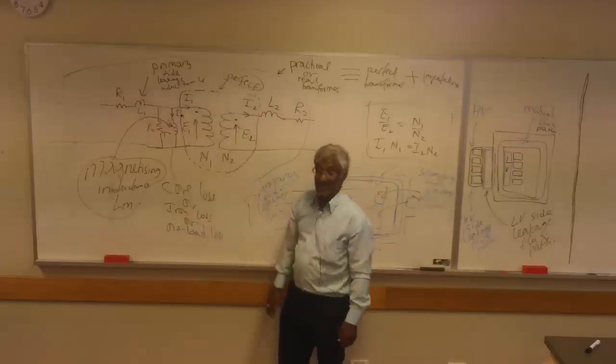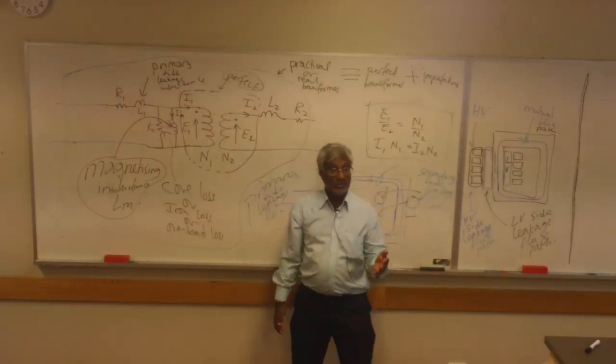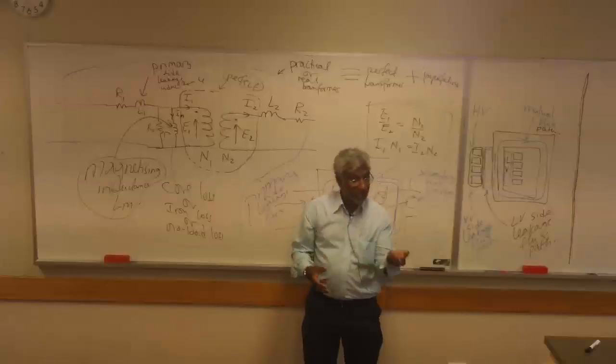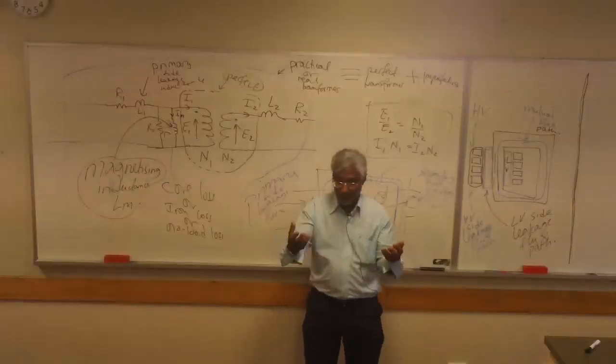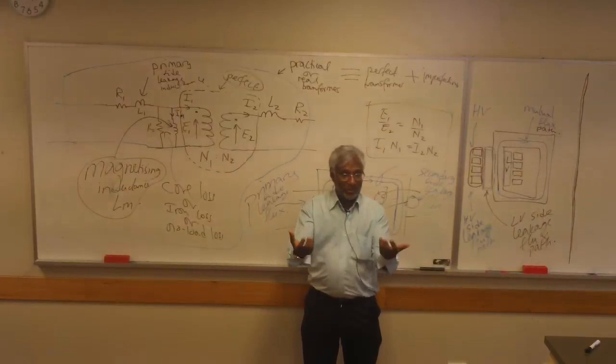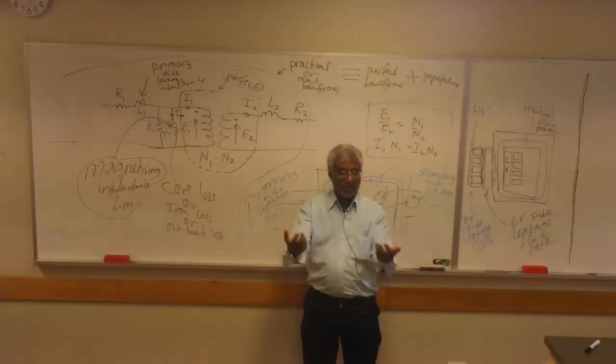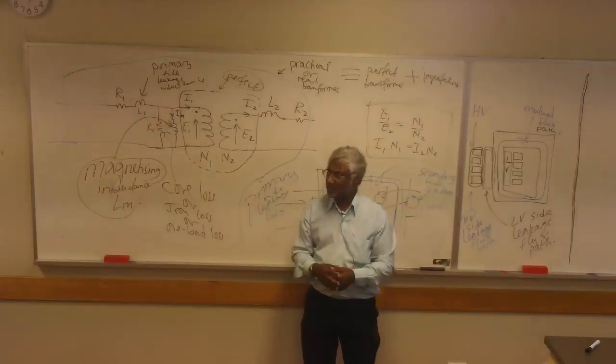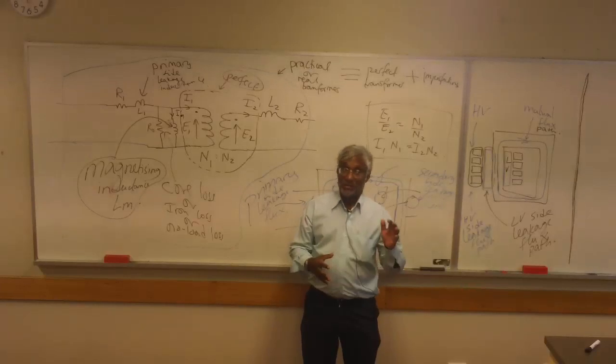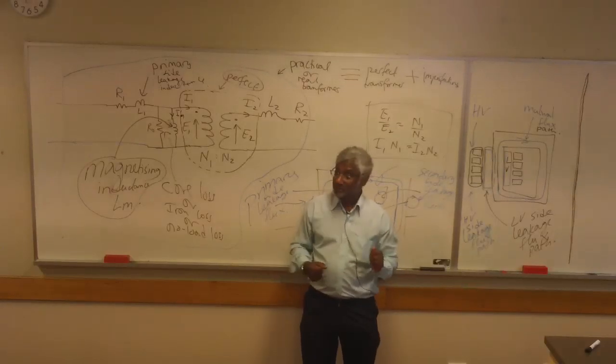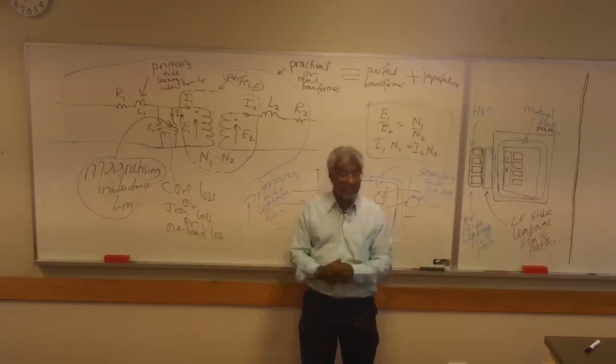Because you've got HV copper, LV copper, and in between them insulation. Any other capacitance? That's right. Winding to earth capacitance, or winding to core, if you like.